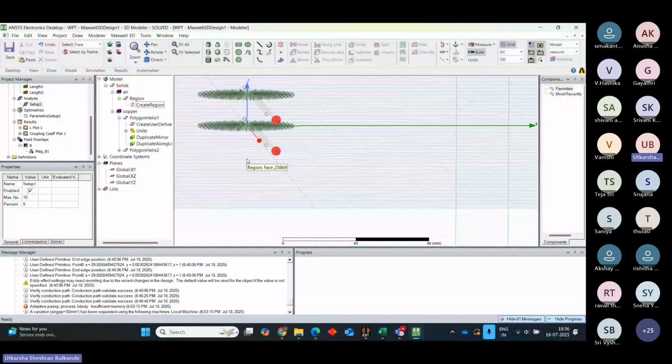Yes, ma'am. Also, while designing your hardware, you will decide some dimensions for your coil: distance between the turns and number of turns. These parameters you decide to get a particular inductance. When you are deciding these factors, you have to simulate in some FEA software to see if your assumptions give you that same inductance or not. Whatever mathematical calculation you have done, to validate it, you can go to FEA. Understood?